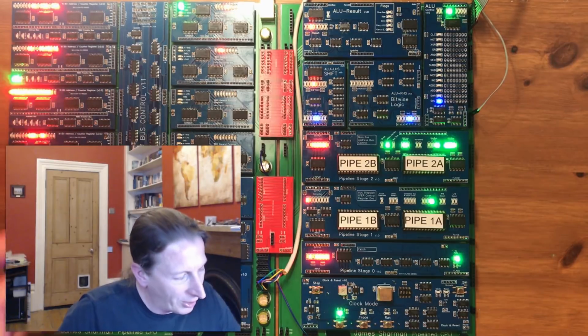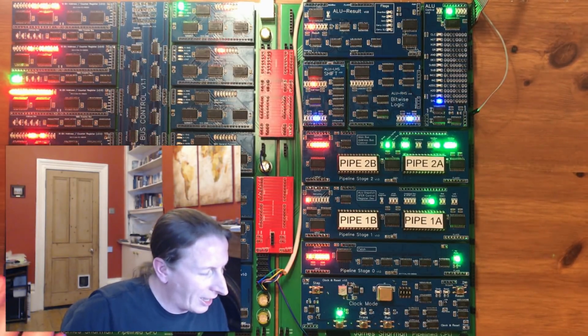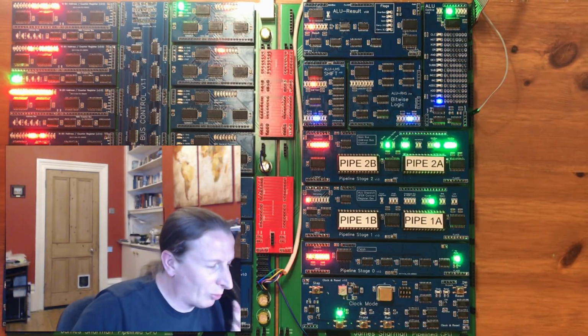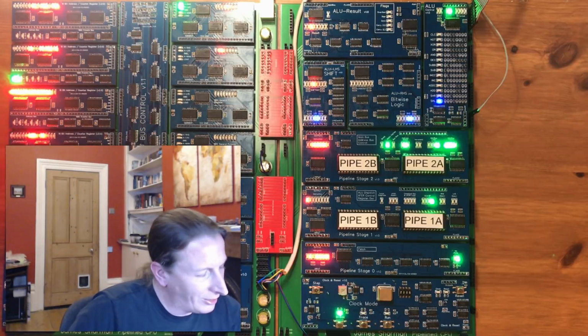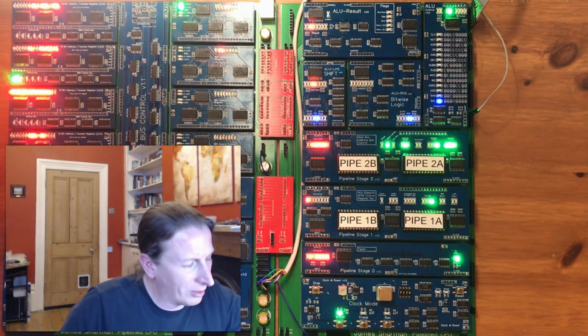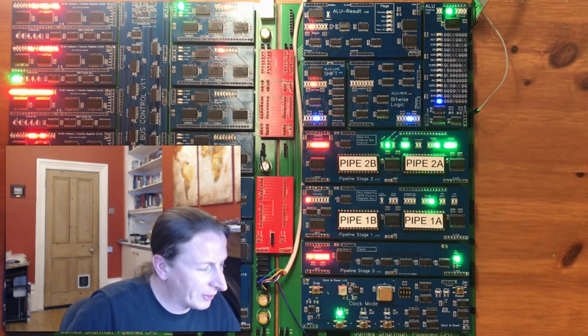The transfer bus is the least utilized bus in the processor, and it exists really and truly for one reason and one reason alone. I need to be able to move 16 bits of data into the program counter to perform a jump or a function call, and I need to be able to do it in a single operation.